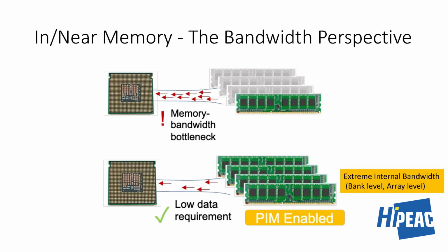And how much do we get, like 1000x increase in your memory bandwidth, right? Because now we are not bottlenecked by this serial link or parallel link, right? It's a parallel link, DDR is a parallel link. But we are directly embedding compute elements here, so we have direct access, and so you increase 100x, 1000x in the bandwidth.